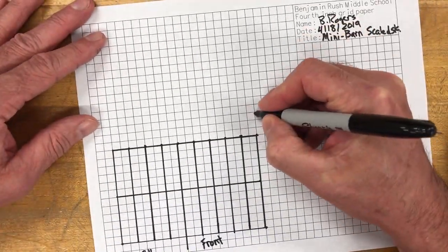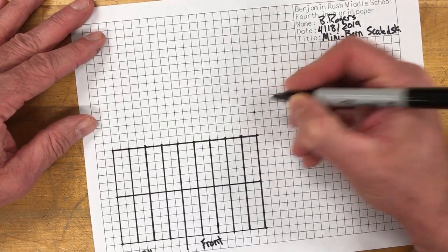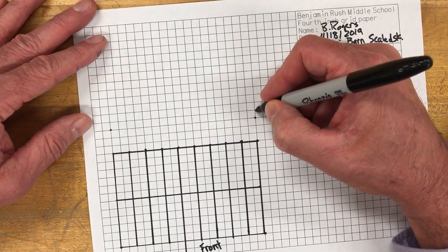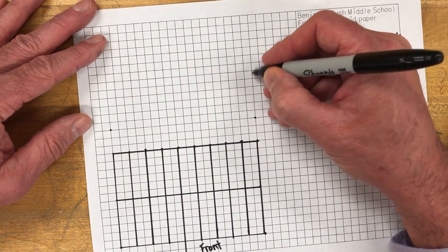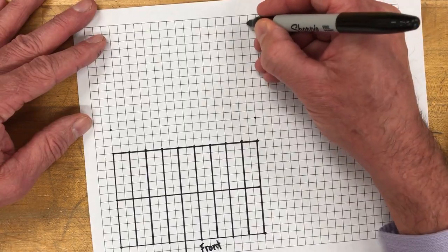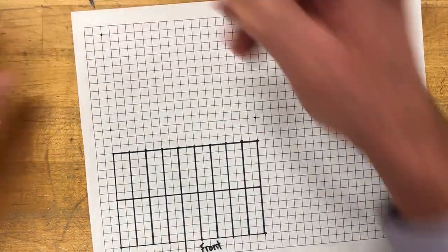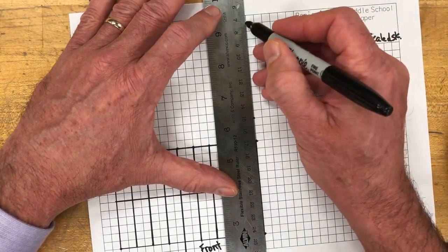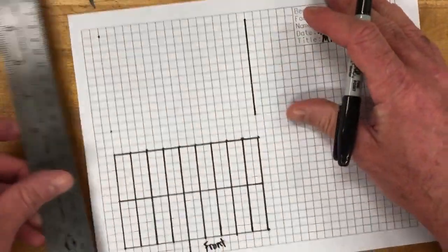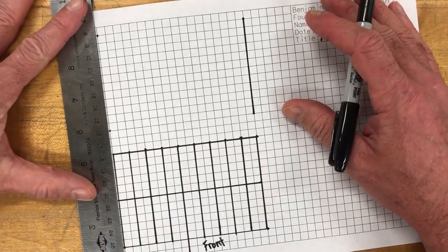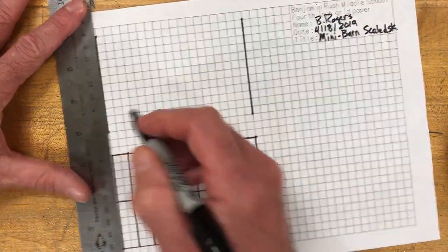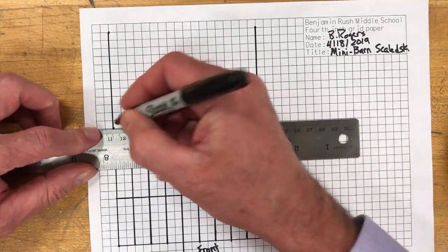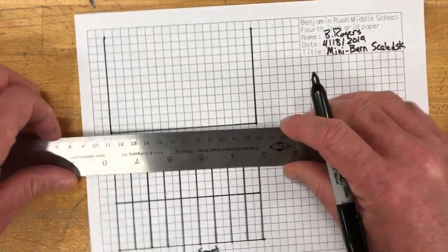I'm projecting about, let's go with 3 units of space between there, just projecting along the grid lines. I'm counting back 12. 1, 2, 3, just barely fits on there, which is fine. So I'm going to draw a couple of vertical lines there for the sides of the barn, the ends of it. Need a horizontal line here. It's basically a rectangle in the top view as well.